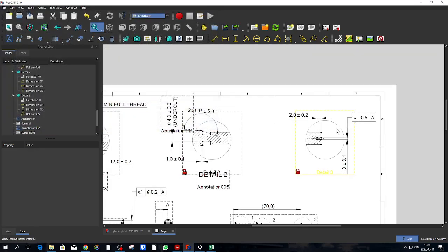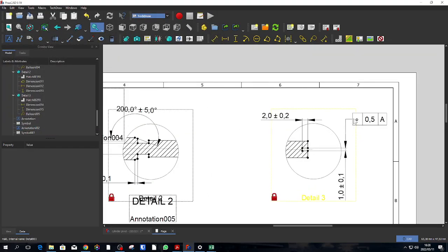Okay, so just to explain this symmetry GD&T, because it is in line with the dimension, what we are saying is that the mid-plane of this slot needs to be symmetric to within the tolerance of 0.5 millimeters relative to datum A. That's why if the leader line of the GD&T tolerance was separated from the dimension line, it would have meant that we are referring to that face.